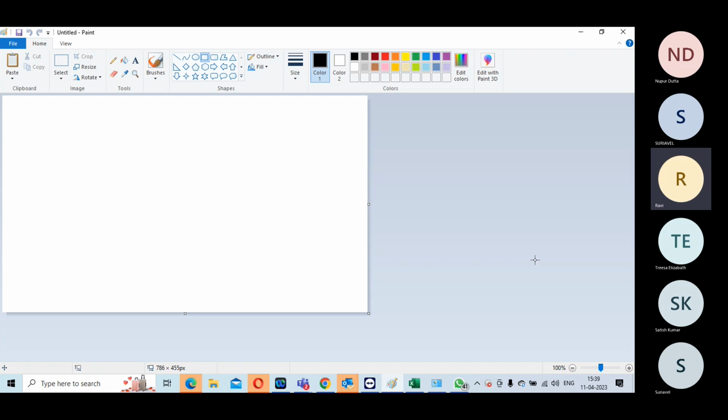That means skew can be that, this is assuming it's a worst path. If I have moved 50 picosecond, that means I have given 50 picosecond to the other side. It has got 50 picosecond extra. So 2x the skew value is the maximum violation you should allow in your placement stage. But my recommendation is try to get it to 0 along with the skew, because you may have something to play with. But up to 2x the skew value, you can allow the violation to move to the next stage.